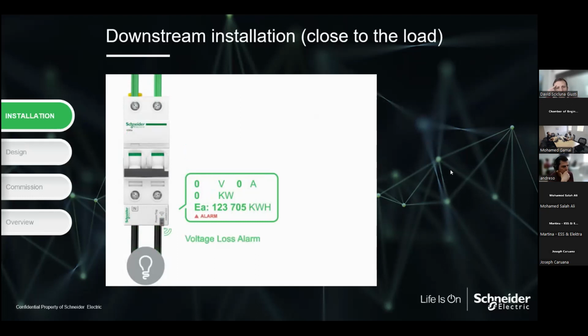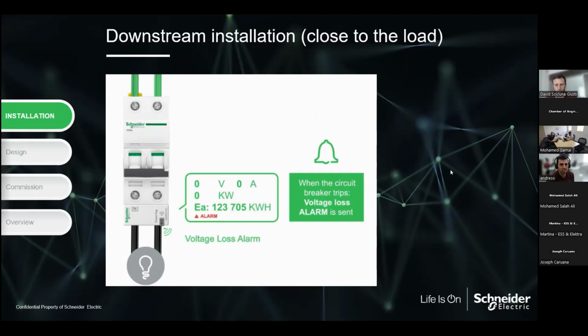And also, what we are seeing here is a simulation, the type of reading we can get from the power tag. As Muhammad Salah said, it is the smallest wireless energy sensor. And I need to stick to the word energy sensor. It is not only a current transformer, it's an energy sensor. So it acts as a power meter to give you the volt, the current, the kilowatt hour, and power factor also. Not only a wireless CT, it's totally an energy sensor, and it has a third-party IEC certificate for that.